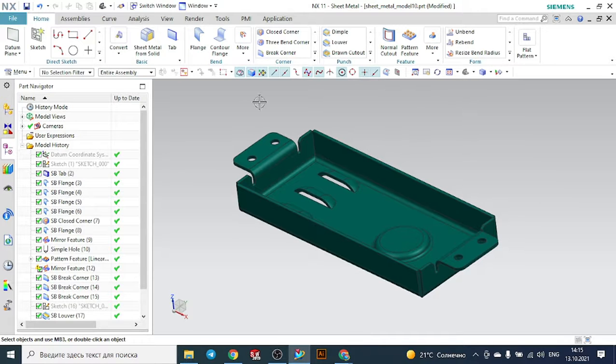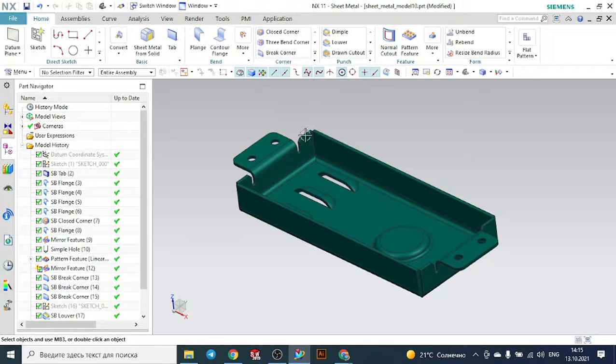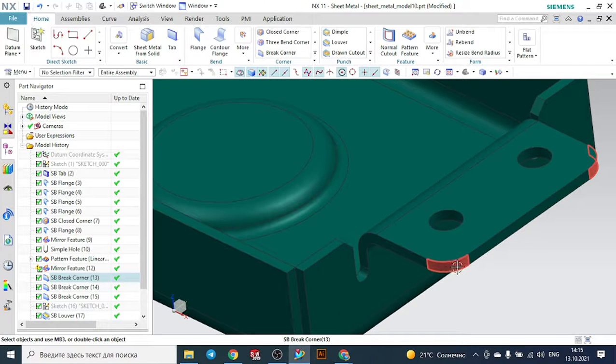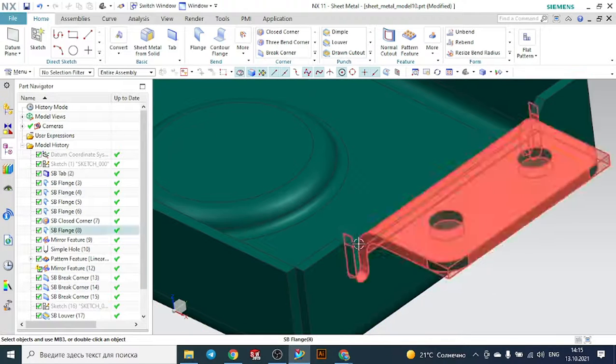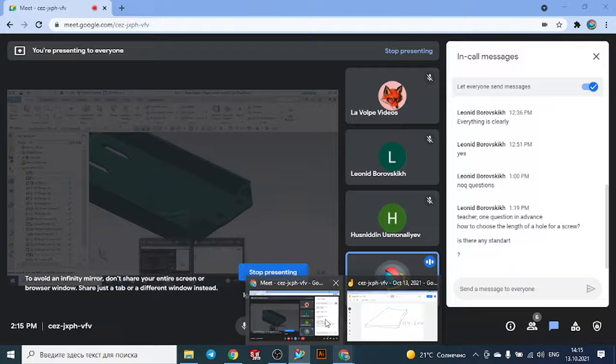The important thing is to always create starting with the tab and then change its shape and add several features like the holes, like the louvers, the dimples and so on. With the edge blend, with the chamfers and so on you can create your element, your project.